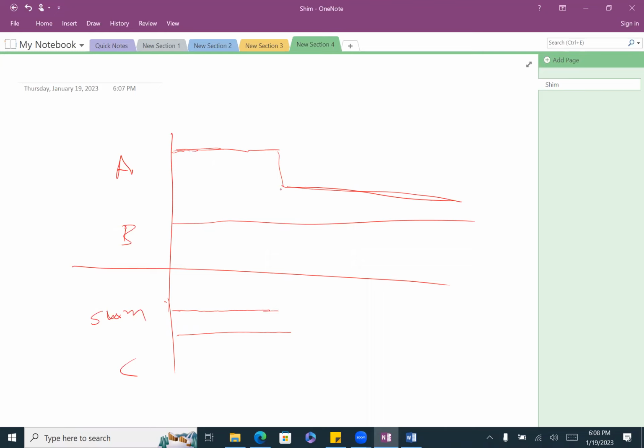All right. Now at this point, what's going to happen? What will the result be? Now, when A goes to 0 and B stays 1, the output will be 1 and the carry will be 0. So the sum should go to 1 and the carry should go to 0. All right. However, in digital design, there is always a delay. Which means here at this stage it is not going to change right away. It's going to take a slight delay, then change. Same thing here.